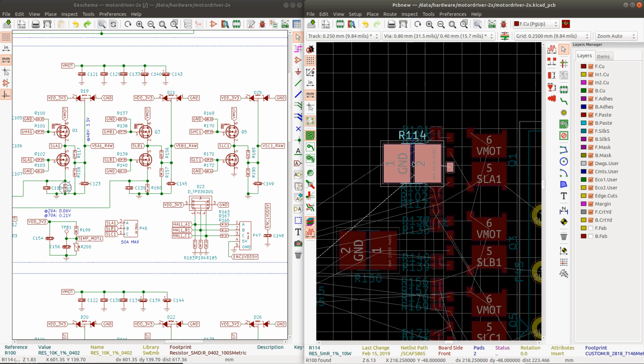And I'm kind of thinking that maybe it's better to move it out just a little bit, and to have like a copper area here, which I connect also to the other side of the PCB, and kind of get a better heat sinking capability of this junction here.